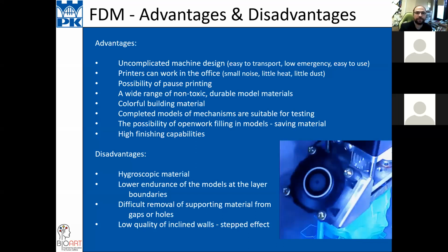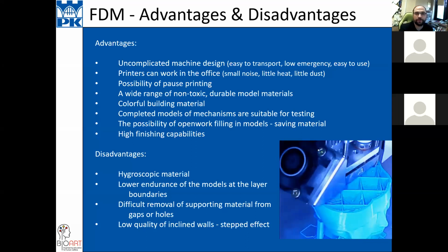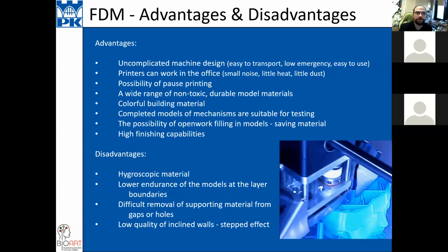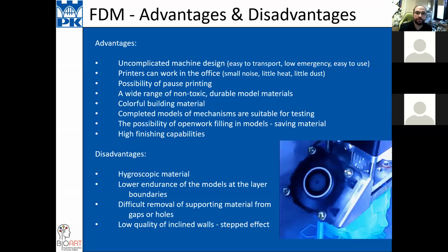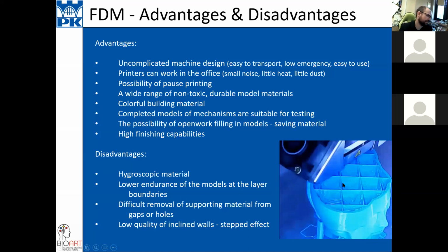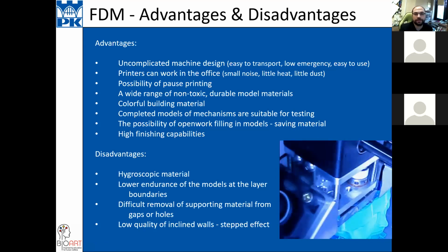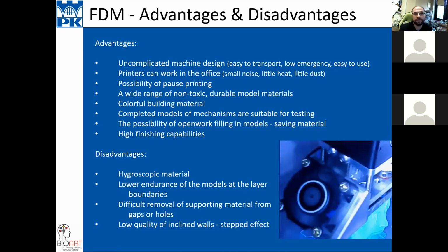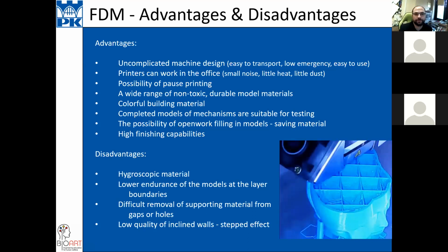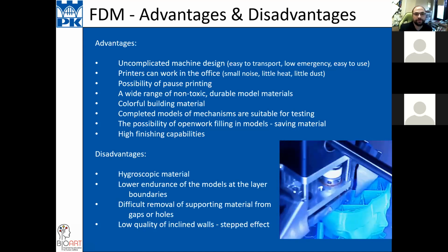The properties of the print will be better, but you must be careful. It works only when you use 100% infill, because you see here we have some kind of 20% infill. When you want to harden in salt or in a different kind of material, you must have 100% infill, and then you can harden your prints after printing.